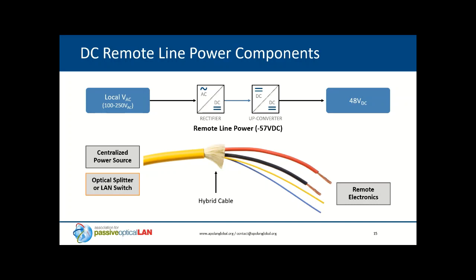You can see here an example of a hybrid cable where you do have 2-strand fiber as well as your copper conductor for your power pair. You can also split that up. There's no rhyme or reason to it. That's more of a dealer's choice on how they see that fit. Part of what gives us the availability to do this is NEC Class 2, and we'll cover the Article 725 very briefly here in the next slide.